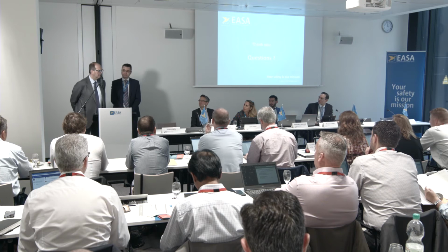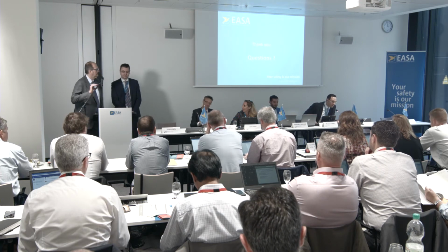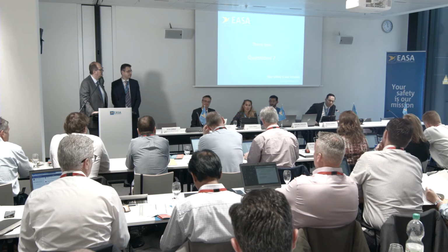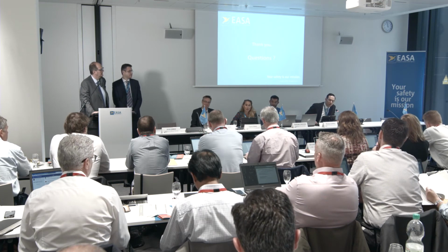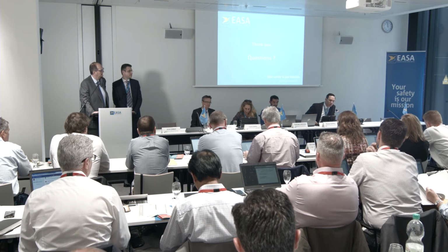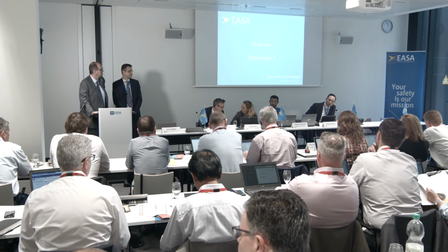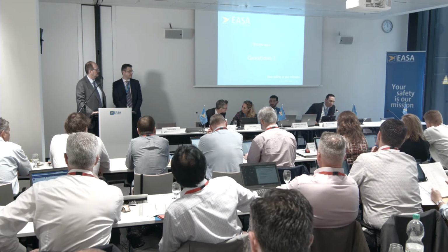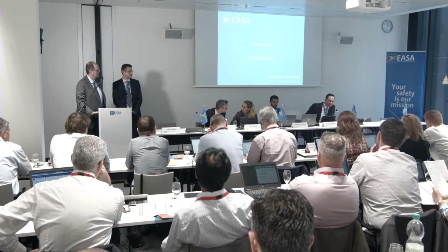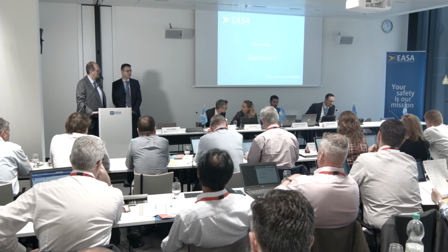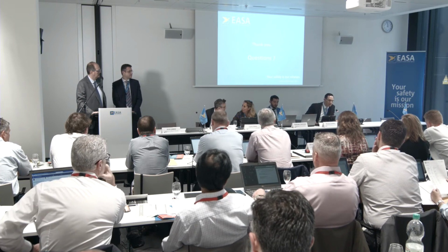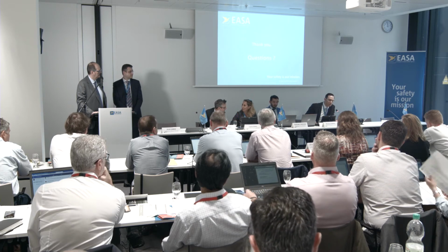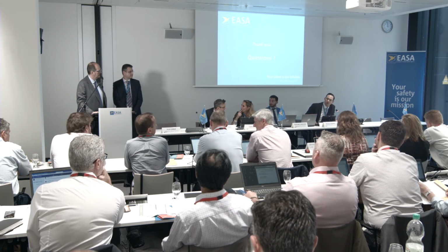Can you repeat the question? I didn't get it, sorry. So there is an STC or a change to an STC, but it was actually not done originally by a European DOA, but by an American organization. Okay. It was classified basic as per the current TIP Rev 6. A basic STC or basic change to an STC has no EASA involvement, meaning there will be no EASA certificate.